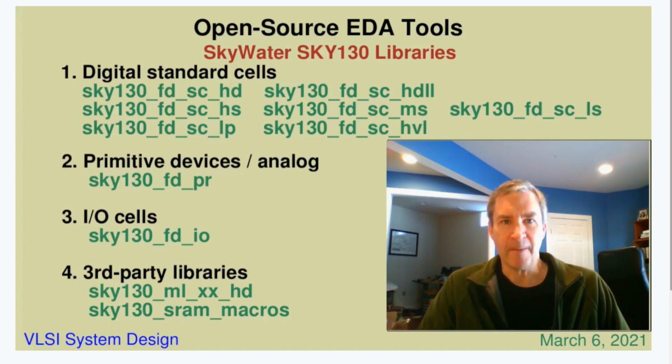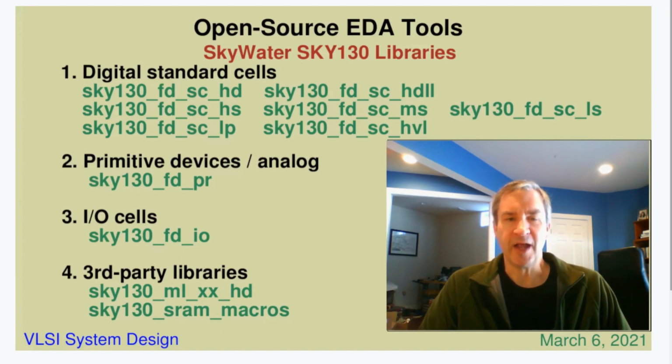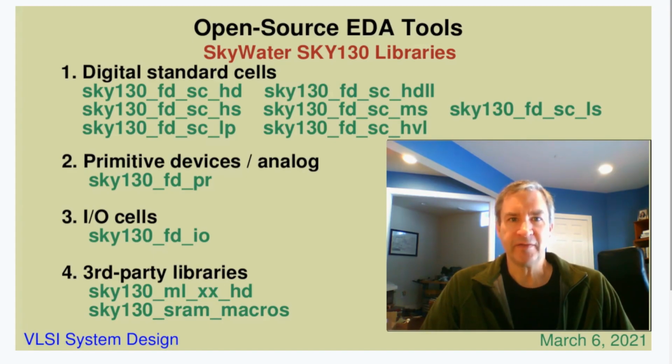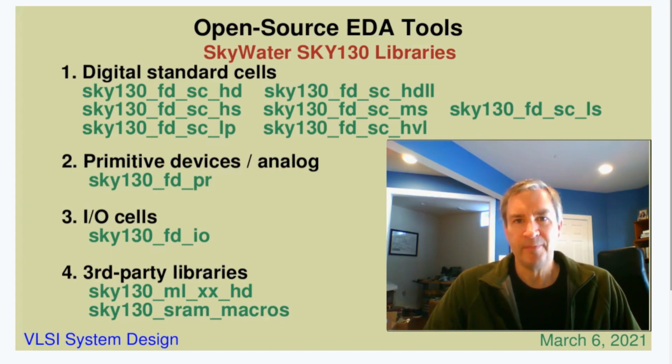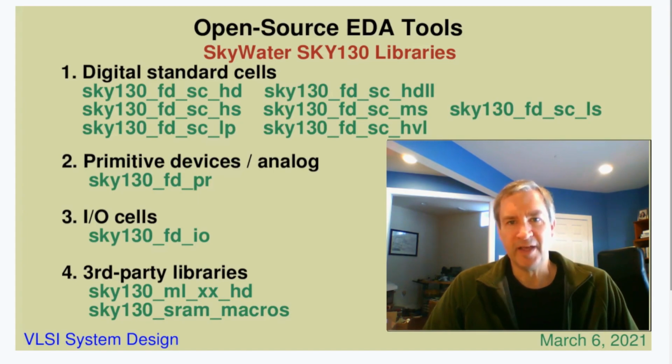SkyWater PDK. This is the library of analog components. Most analog components, such as basic transistors, are handled by extraction and don't need library components. However, many components have one approved layout and are easiest to deal with by treating the device as a component of an IP library. Such devices include RF layouts of basic devices, bipolar devices, ESD devices, parallel plate capacitors, and so forth. Devices operate from 1.8 volts up to 20 volts, with the most common supply voltages being 1.8 and 3.3 volts.